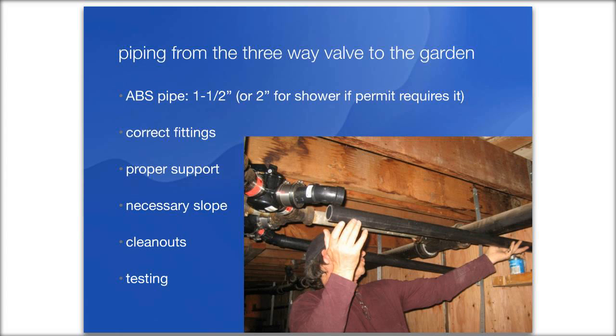That's the correct way to do it. It would be difficult to run a vent and have it connect because it's supposed to connect to the bathroom sink vent above the flood level rim of the bathroom sink, which would mean you'd have to be able to get up into the wall to connect those vents, which would be inconvenient at the very least.